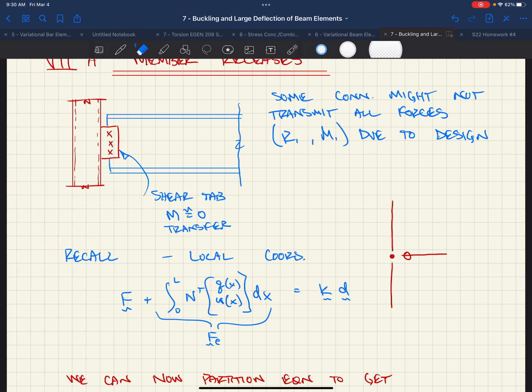If this was all steel frame and it had rigid diaphragms, big concrete diaphragms, and stiffness really plays a role in where everything is going, then in that case the model is the best approach, because VA, or RAM or RISA, is going to take into consideration the fact that your diaphragm changes depth, right? So the stiffness of your diaphragm changes as you go across the diaphragm. It will take into account the fact that you might have a brace frame that has an aspect ratio of 1 to 1, and you might have a brace frame that's 1 high and 2 long, so now it's a lot stiffer than your brace frame that's shorter.